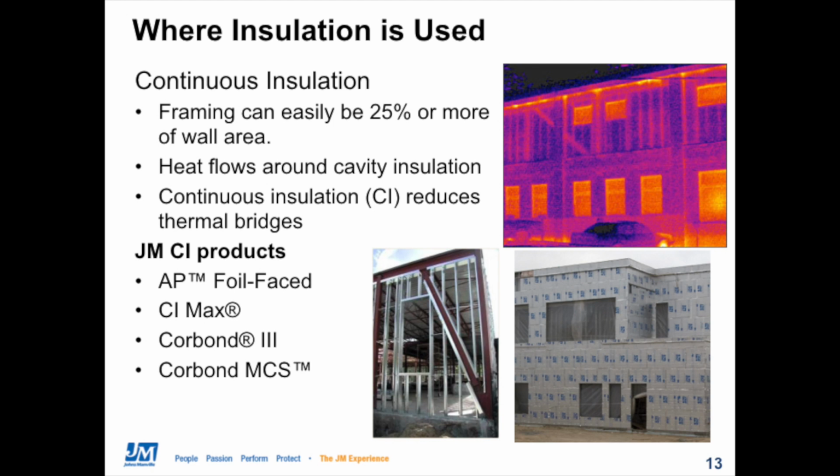as exterior continuous insulation. When it's used as CI, specifically spray foam, is also usually applied to the outside of a building. And when it's used this way, closed cell spray foam provides continuous insulation as well as air sealing and water protection in one step.